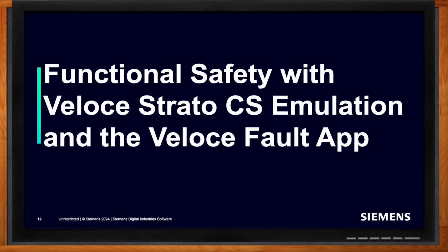Yeah. So basically, what we're seeing is that, as the designs are scaling in complexity and things like gate count, we're seeing a real big push to move away from traditional hardware based safety mechanisms, things like ECC and parity, and moving to more of a software based safety approach.